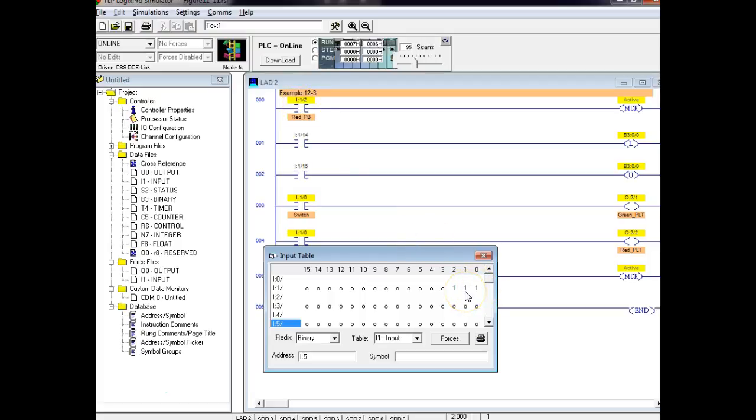If the switch is open, it sees that as a 0, period. And then what does the program determine is true and what is false? We've got this set up for examine closed. We're getting back a 1, so a 1 is true, right?